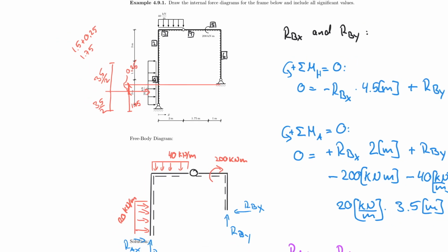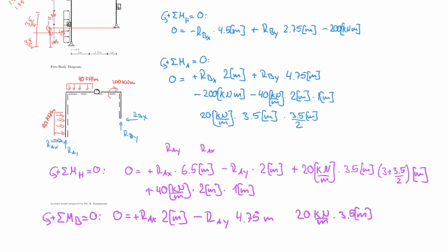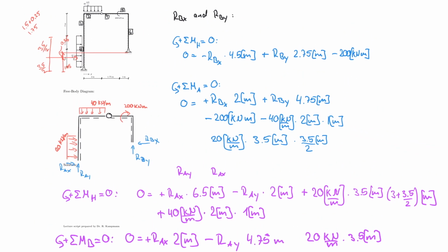So that means that our lever arm is actually 0.25. That is a little bit tricky, so that's why we're solving this problem here, but my lever arm is 0.25 meters. And it's below the support, so the resultant here is actually below this point, which means that we're rotating counterclockwise. So therefore this becomes positive.